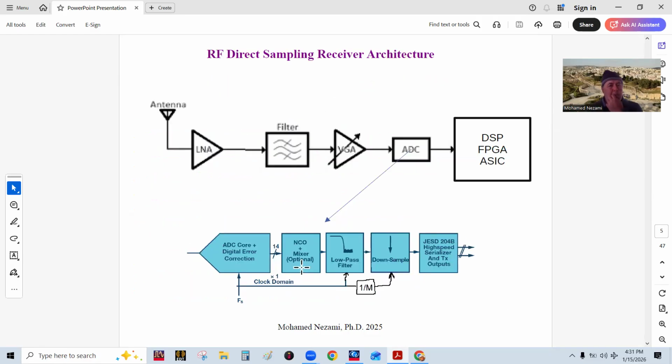All right, so let's just refresh your mind on this. What we're doing is basically we have an RF front-end receiver that is made simply with filters and amplifiers. We may have a duplexer in here, depending on the duplexing scheme, whether it's time division duplexing or frequency division duplexing. But we don't have any frequency conversion, as you can see. The frequency we go in is the frequency that hits the A to D. And then, of course, we have the DSP section here.